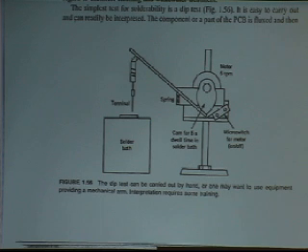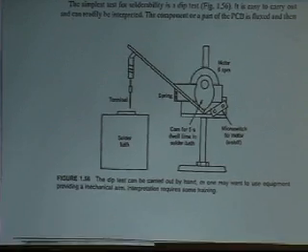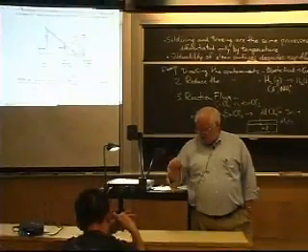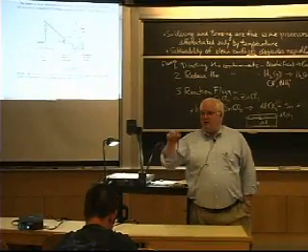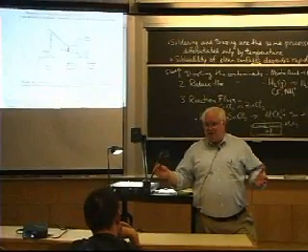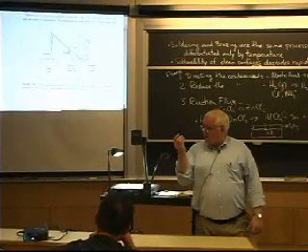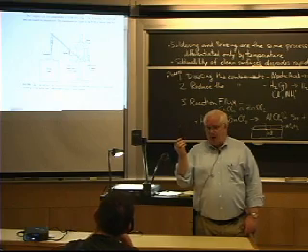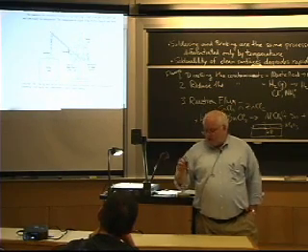And so the simplest dip test is you basically just take a copper wire and a hot plate with some flux on top of some molten solder, and you dip the wire in there and you pull it up and you say, well, did it tin or not? Did it get any solder on it when you pick it up? Is it silver color or is it still copper color? Well, they get more sophisticated.